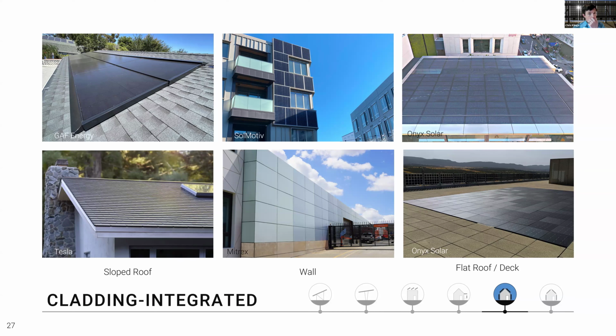PV integrated wall cladding is now being offered by various manufacturers with various surface treatments that reduce solar production, with the benefit of customizing aesthetics and concealing the solar technology from view. Integrated solar floors, similar products can be integrated into a rooftop deck or balcony with the same methodologies utilized for pedestal-mounted pavers or deck tiles. In such an application, textured glass is typically utilized to form a non-slip surface.